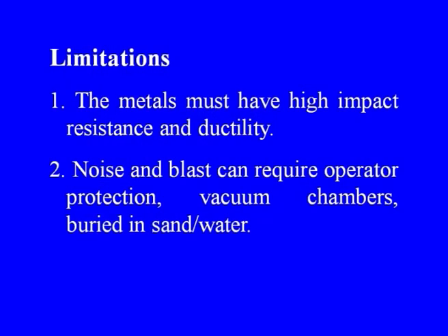However, there are a few limitations of the process. These limitations include that the metals must have high impact resistance and ductility. Mostly the brittle materials cannot be joined in this process because they may get cracked.